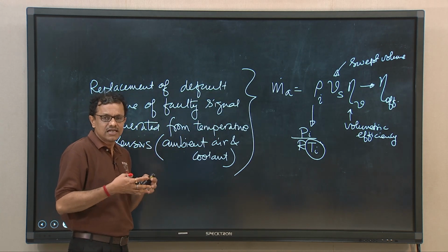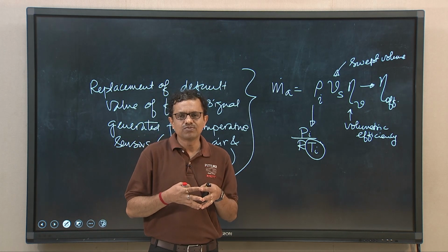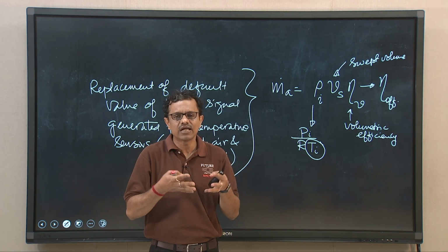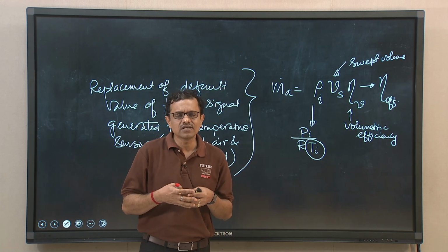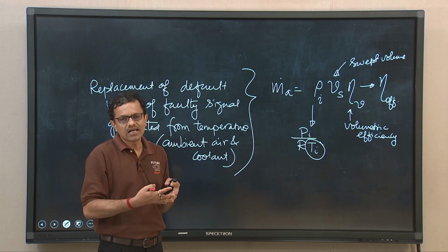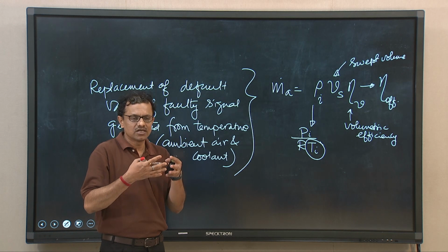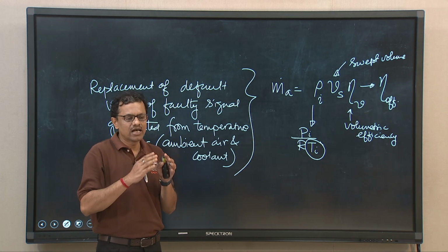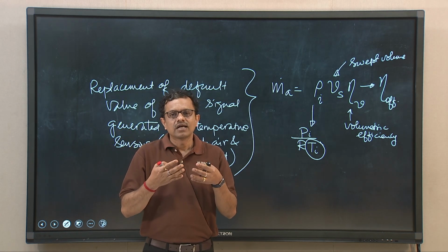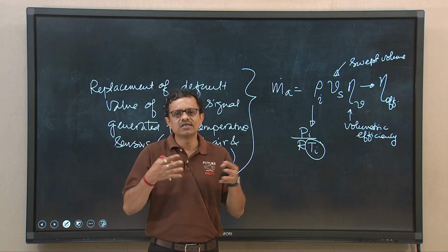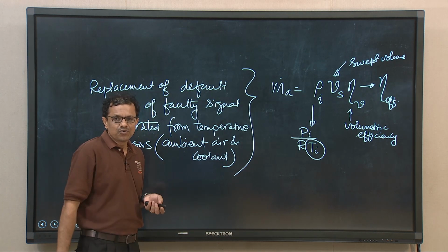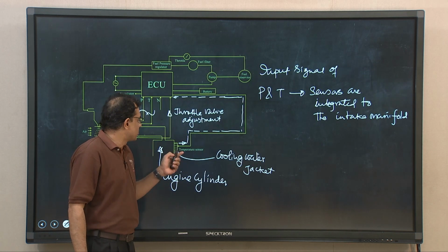If the airflow, or the amount of intake air drawn into the engine cylinder, is not at par with the theoretically calculated value, then it will have detrimental consequences. Either combustion will not be complete or efficient, and the exhaust gas that comes out will be rich in oxygen, which will also cause overheating and make the catalytic converter run beyond its optimum efficiency. And most importantly, power output will be less. So, this is very important.